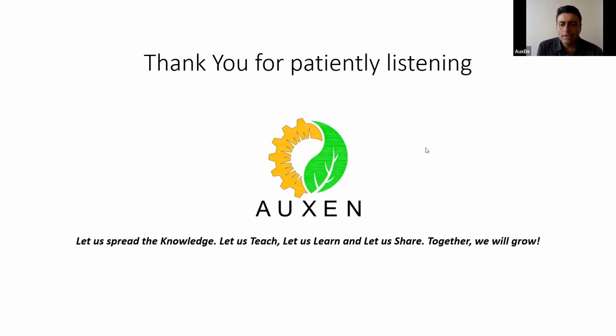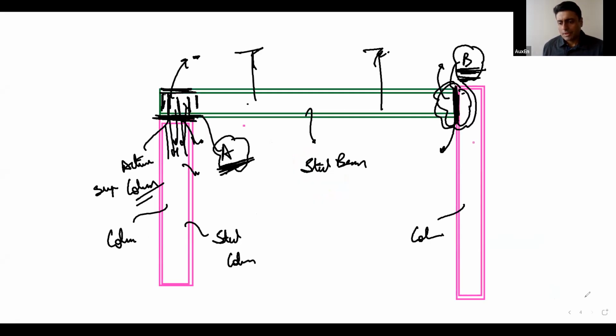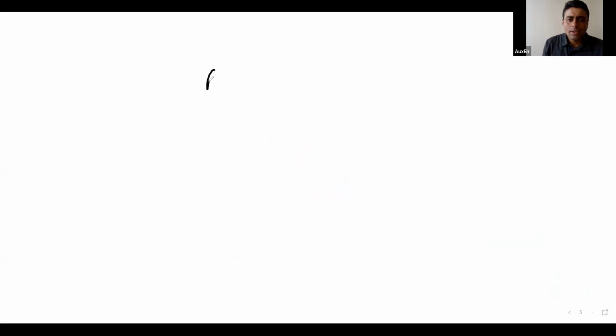Mr. Venkatesh is asking, how do we achieve the strong column, weak beam concept in practice in steel structures if all joints are rigid? No, joints can be rigid. See, you are getting confused with two things. Joints can be rigid, but still you can develop a system where the beam is not as strong as the column. You can develop this, and still the connection can remain rigid.